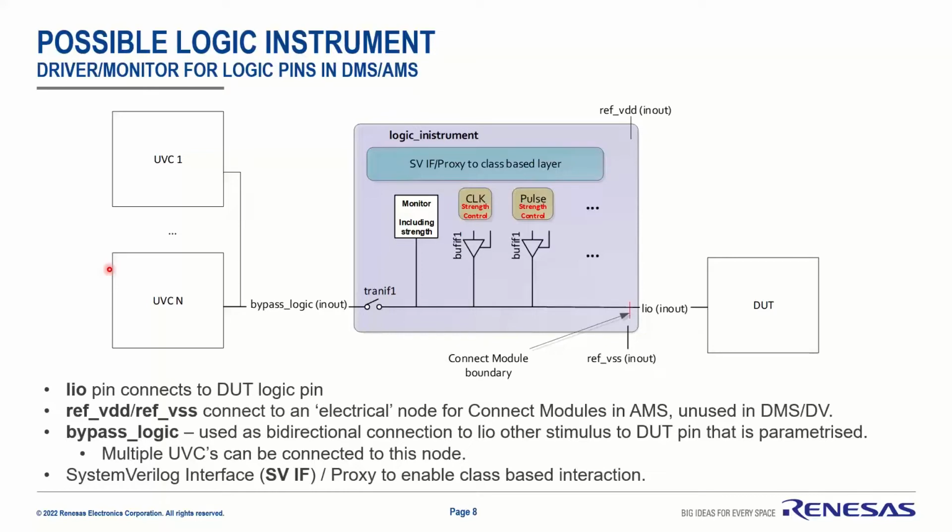So a possible logic instrument for a driver monitor is depicted here. The way I've done it is I've got a SystemVerilog interface that then connects to an API that I can then speak to from the test case itself via the software layer.